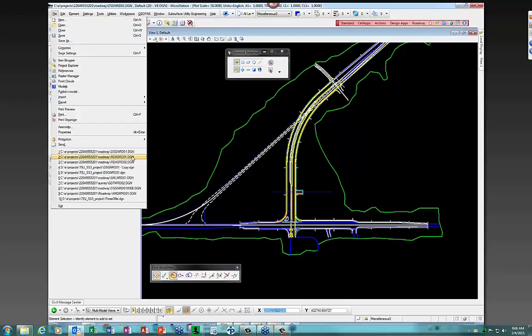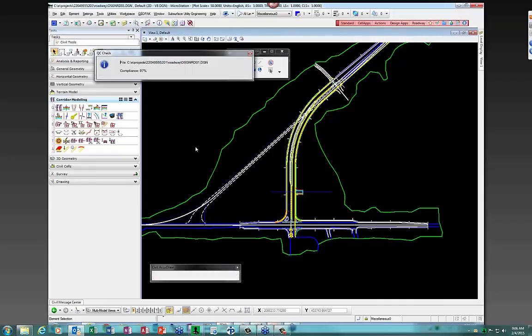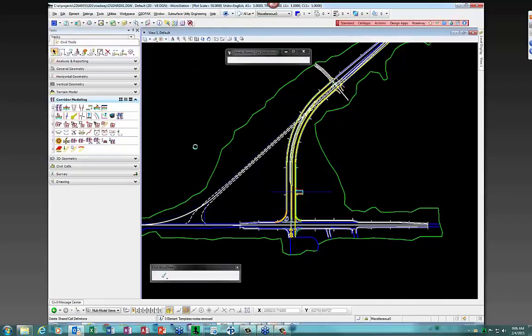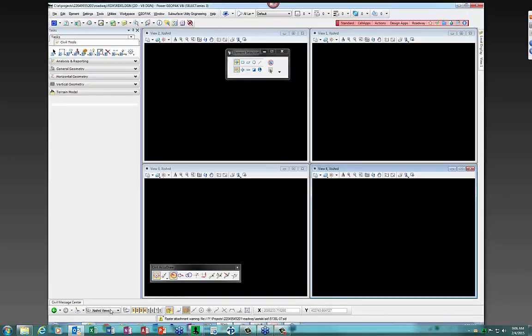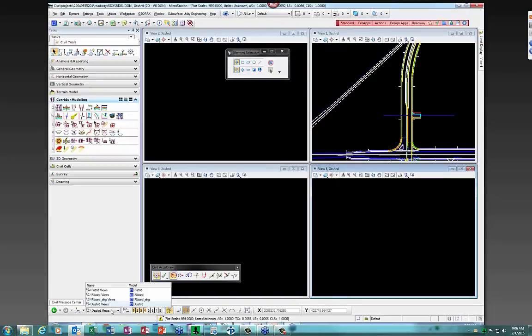And if you don't know how to create a cross-section sheet by now, you can use the Create Edit tool or the Create File tool, and it will create a cross-section design file. In that cross-section design file are several different models, and like I said, if you've been doing FDOT Roadway Design for a while, you know what each of these are. But the last one here is where we typically would put in the shapes for cross-sections and criteria.